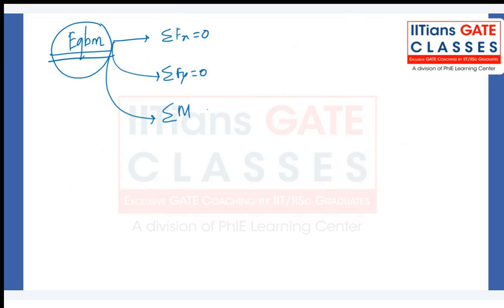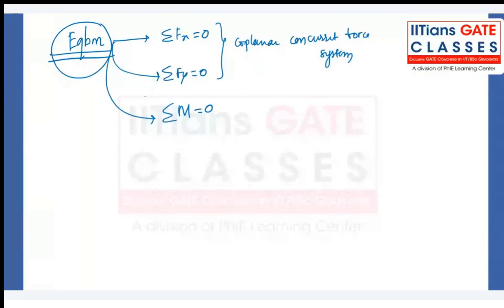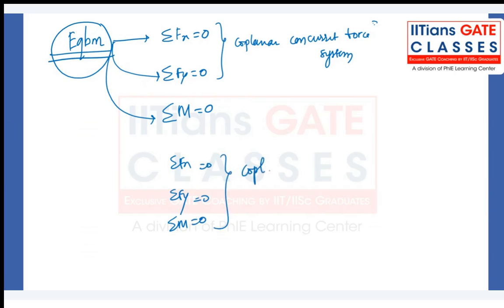Out of these three, these two you will apply in case of a coplanar concurrent force system, but you have to apply all these three in case of a coplanar non-concurrent force system: summation Fx, summation Fy, summation M equal to 0.